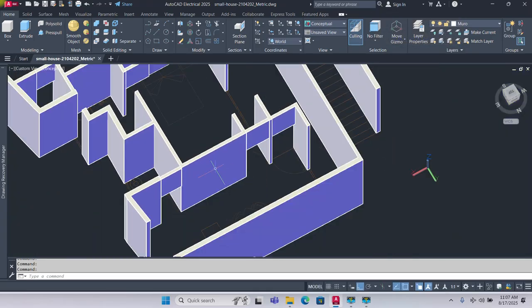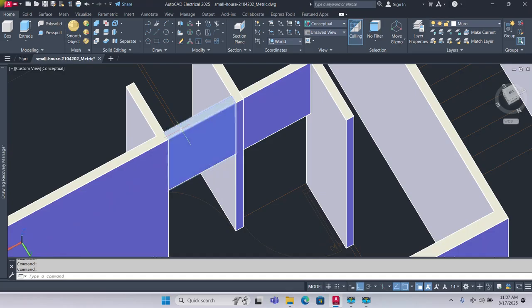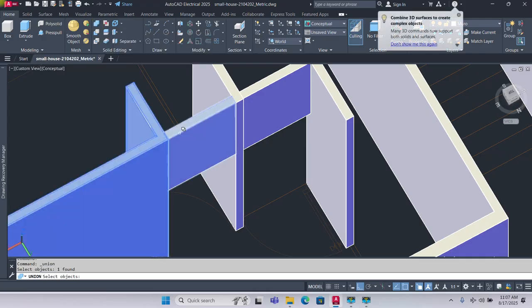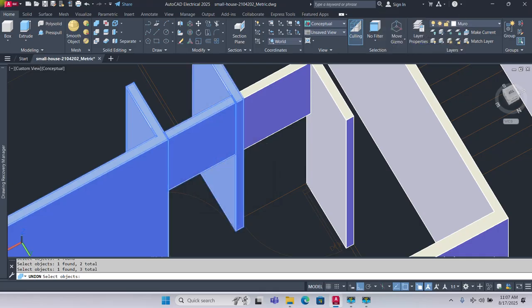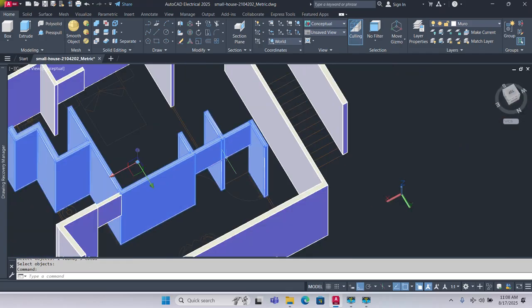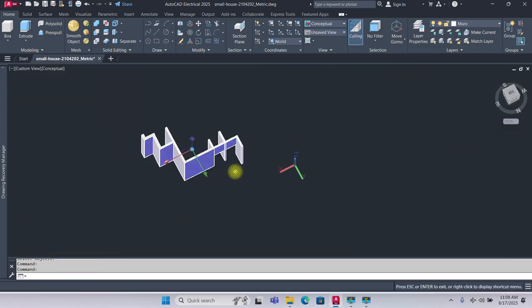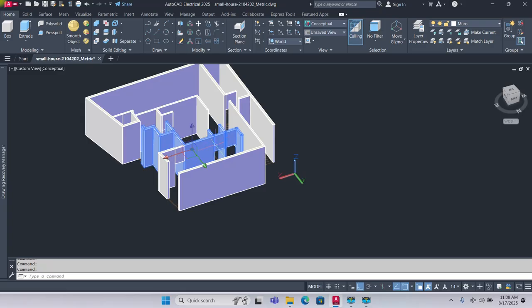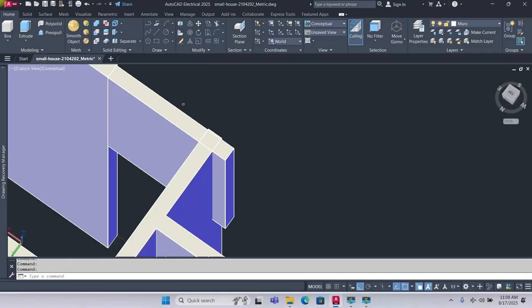And the other thing you might want to do is, if I want to turn this into one object, you can use your Boolean operation. So you have these solid unions. Just select this and select that. I want the solid to be selected. I also want this to be selected, and that and this. Just press enter. They will become one object. You can see that they are now one object instead of having that top as a separate object. Okay, so you do that.